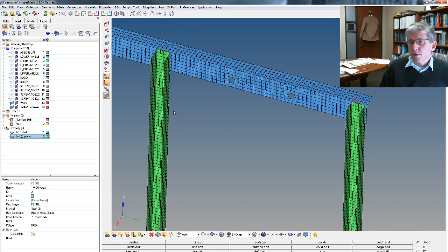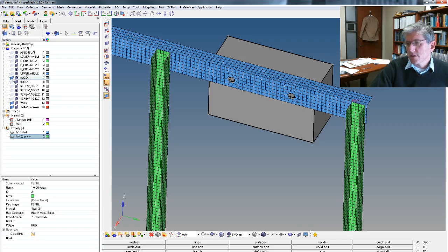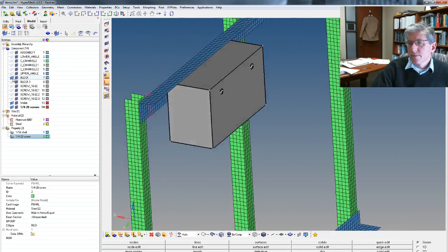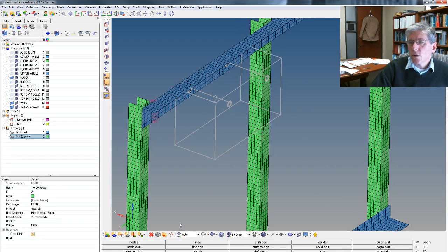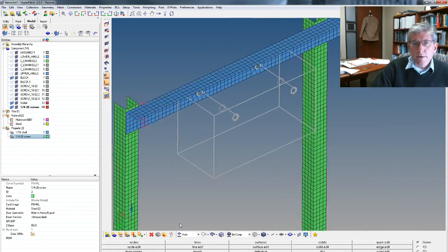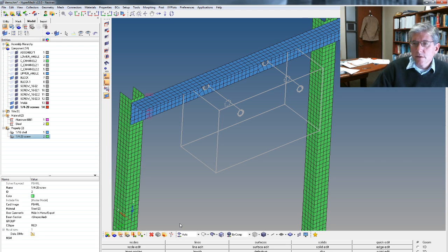So, for example, we need to put the electronics package out here. So, where is it? Where's that block? There's a block. Actually, it's out here. All right. So we know the weight of this is 0.37 pounds, and basically at the center here. So we can put a concentrated mass right in the middle of this block. All right. So we'll need a node there. So let's create a node.